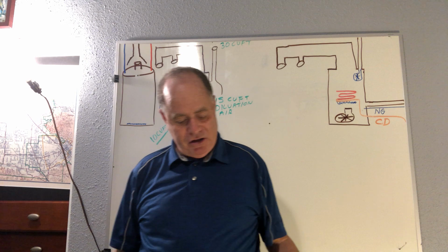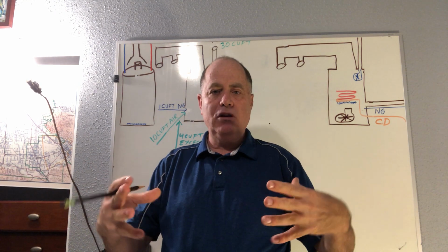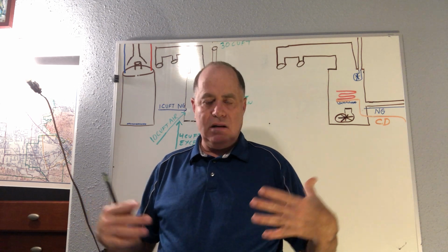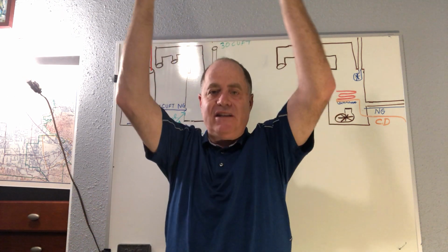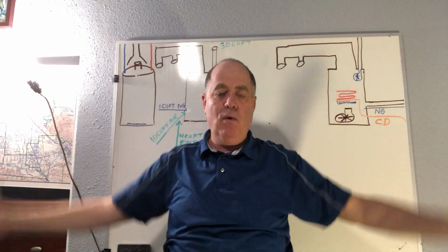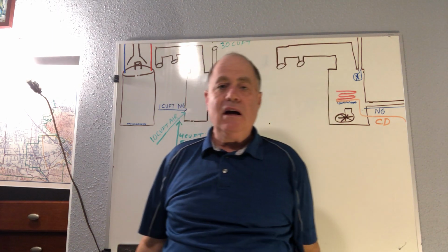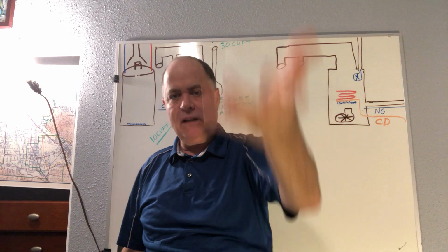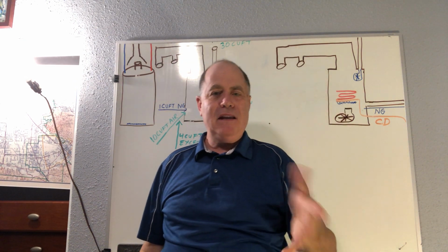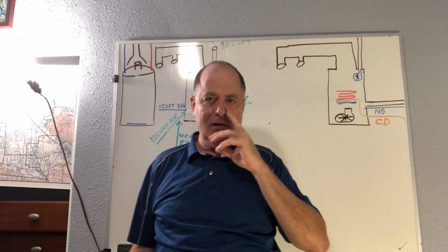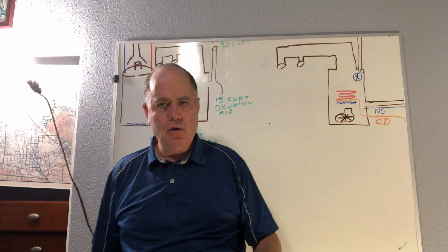Now, natural draft combustion means that it's just allowing the natural airflow to come into the heating appliance and mix with the natural gas and create ignition, and then those warm gases rise up in a negative pressure and go out a chimney pipe, somewhat like a fireplace, where the warm combustion gases, the smoke essentially, would go up the flue pipe, up the chimney pipe. A lot of this chapter is about that, and I'm going to go over some different concepts and try to get you updated about some of the newer equipment.